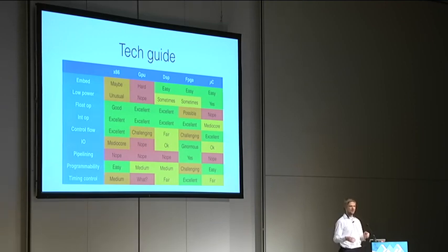And then you have a microcontroller. This chart basically shows that, for example, if you want to put an x86 on your quadcopter for doing something fancy, you may have a power problem, because those are kind of power hungry, and embedding x86 processors is challenging, at least. Nowadays there are good one-board computers. But if you have a 240 volt power cord going down from your quadcopter, that's not very helpful. They are very good at floating point operations, obviously integer operations and control flow stuff. Control flow is all the if and else and break and jump and continue.